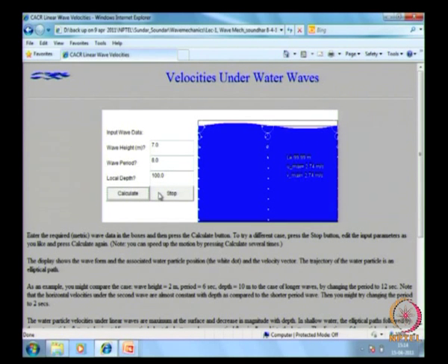So you look at the orbits here. Near the free surface you see a large orbit, that is, the displacement is quite large near the free surface, and it is all in circular orbit, because your wavelength in this case is close to around 100 meters and the water depth is 100 meters. So the d by L relative water depth is close to around 1, which is greater than 0.5.